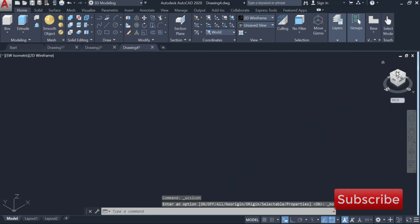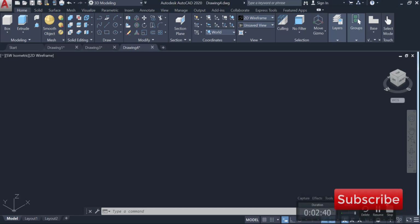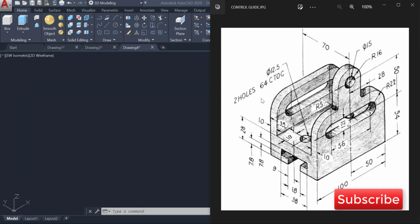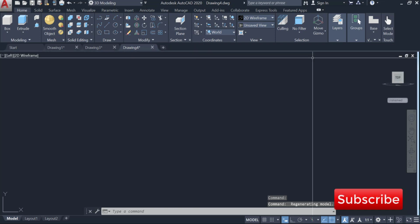So let's start. You can see the orientation of our drawing. I don't know how it went, but let me bring it back. We need to change to this view, the left view, because we need to draw at this point. This is the left view, so click this view and lock it to XY.